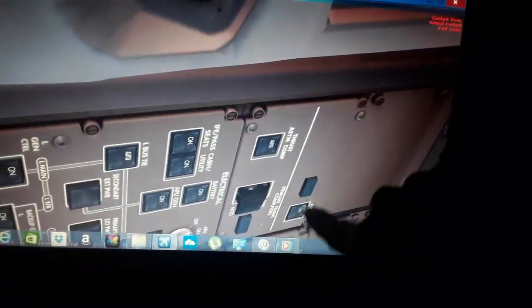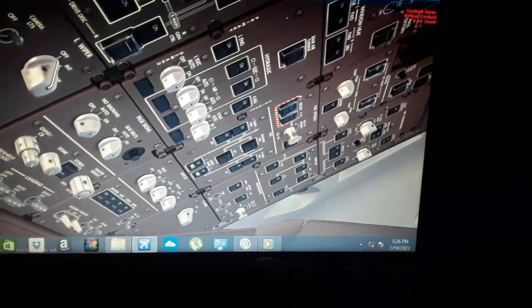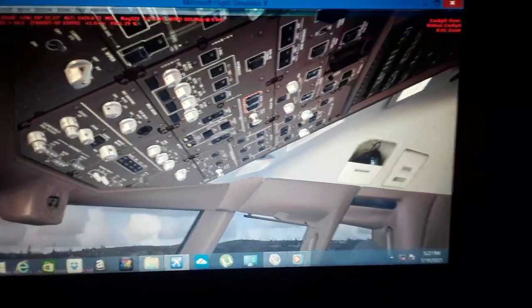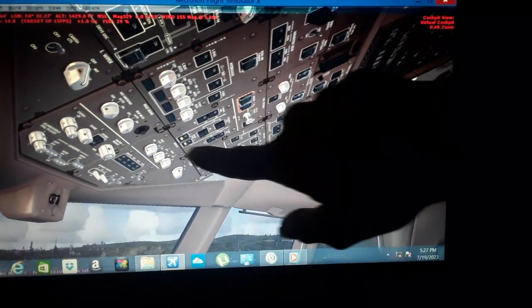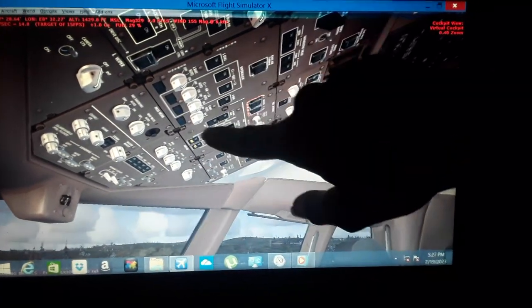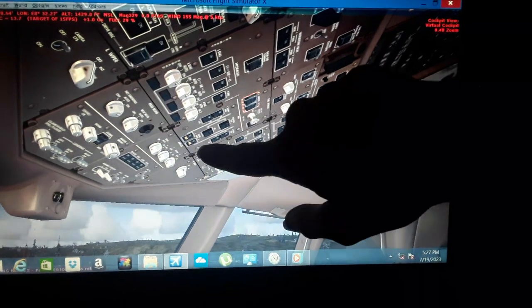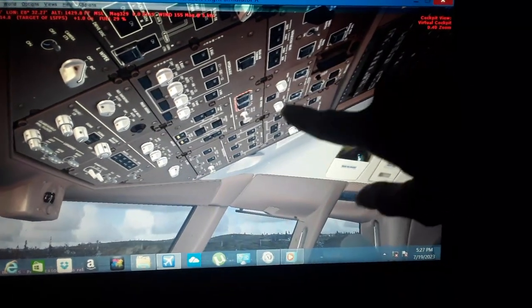The ADIRU, the air data inertial reference unit, I will talk to you about now. The left and the right wing fuel tank, the fuel booster pumps, and the center tank and the crossfeed valves. So this is the fuel system and the fuel jettison. And this is the cabin pressurization and the pressurized air from the left and the right engine, and also from the APU. We need pressurized air from the APU to start the engines, and pressurized air from the left and the right engine for hydraulic fluid pressurization, wing and engine anti-ice. Over here, air conditioning and ventilation, and hydraulic fluid pressurization.